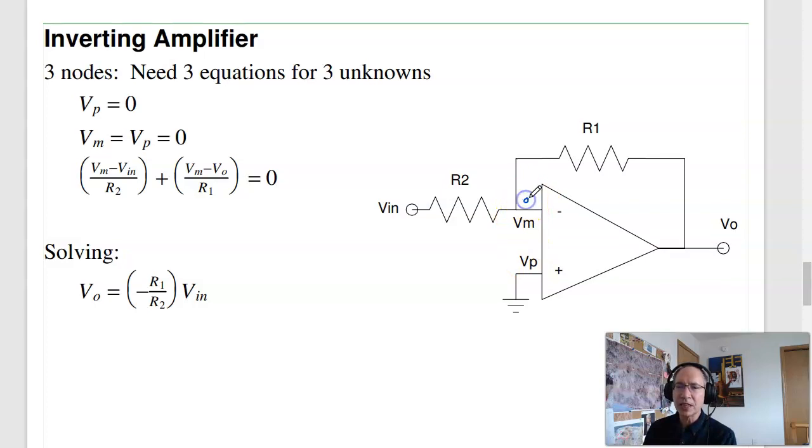It's not actually ground. If I were to ground these together, I would get a different circuit. Remember, this has a finite gain, like 200,000. If this difference is 0, the output is 200,000 times 0. It's also 0. Actually, this voltage is almost 0. It behaves like 0 volts. If the gain is infinity, it actually is 0, but you can't ground it.